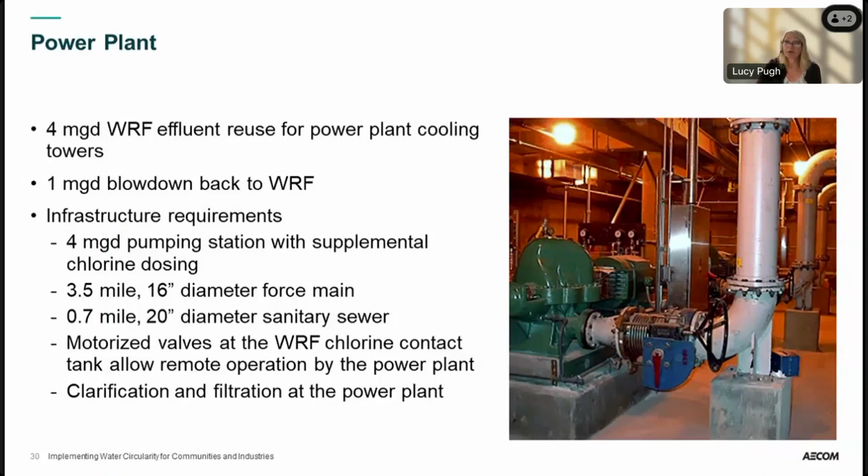There were motorized valves provided at the water reclamation facility that allowed remote operation by the power plant so they can control the amount of water that was coming to them for cooling water use. And then they also provided polishing treatment of that effluent at the power plant before they used the water in the cooling towers.